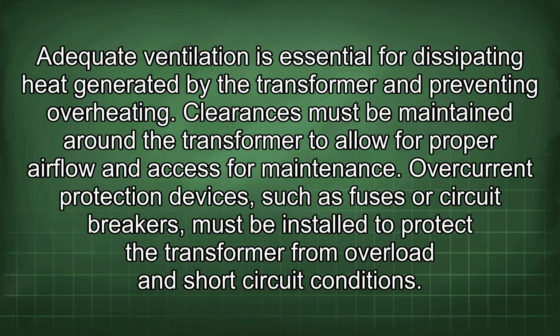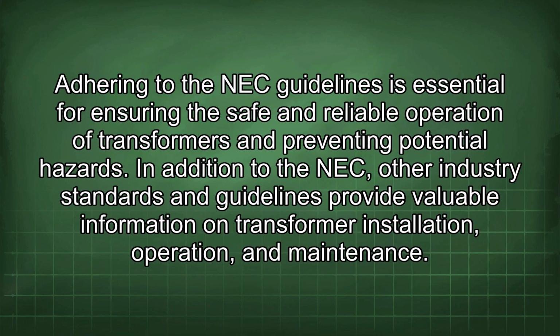Overcurrent protection devices, such as fuses or circuit breakers, must be installed to protect the transformer from overload and short-circuit conditions. Adhering to the NEC guidelines is essential for ensuring a safe and reliable operation of transformers and preventing potential hazards. In addition to the NEC, other industry standards and guidelines provide valuable information on transformer installation, operation, and maintenance.